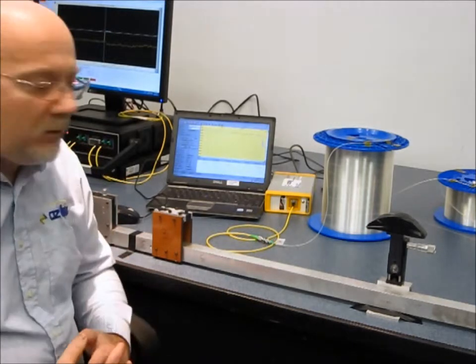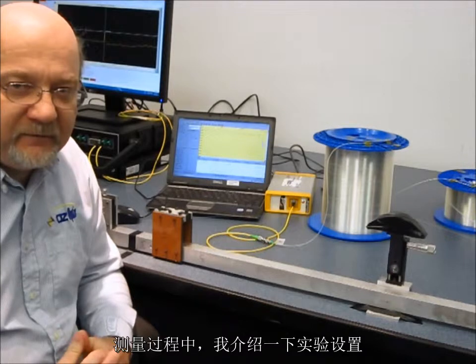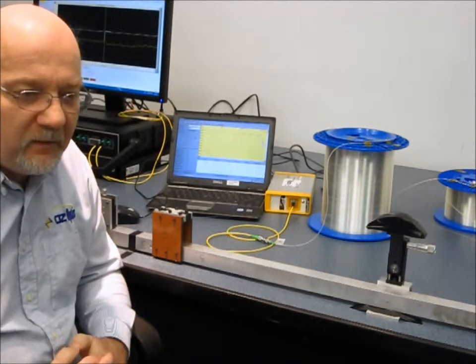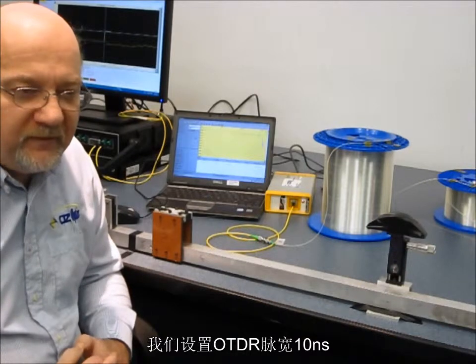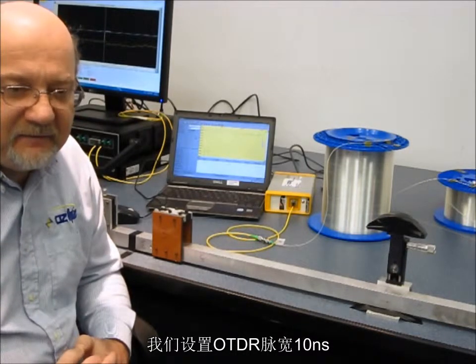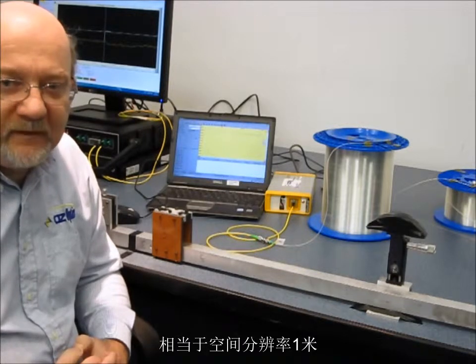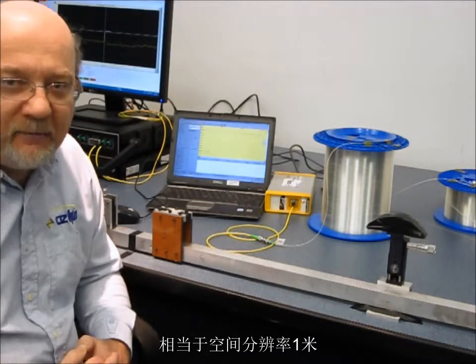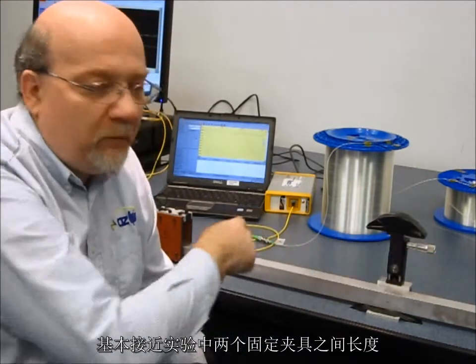While it's scanning, let me tell you a few details about the settings we have used. We've set the OTDR to send out pulses that are 10 nanoseconds in duration. At this setting, it supposedly has a resolution of about 1 meter, corresponding roughly to the section over which we are stretching the fiber.